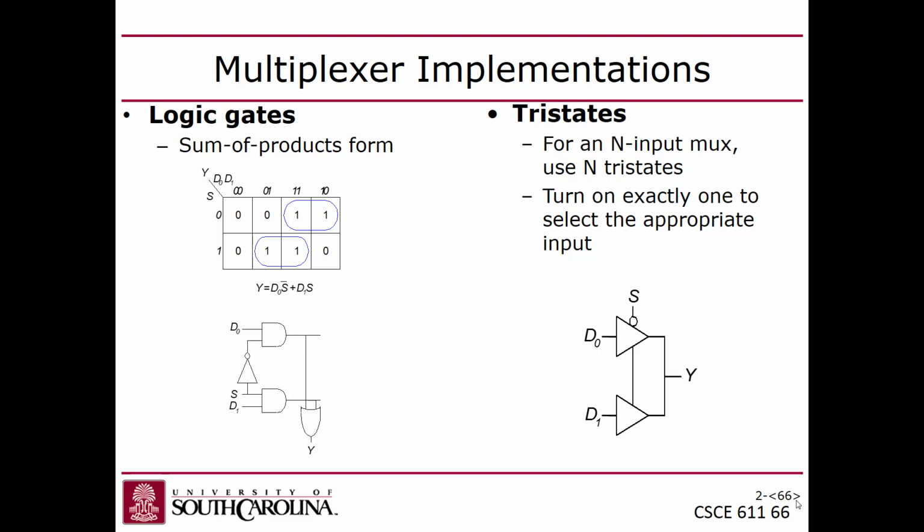Okay. The other way to build a multiplexer is through the tri-state. In this case, you've got two of these tri-states, and you have an input on both. You have D0 and D1 going into the input on two tri-states, and then both tri-states are double driving. Well, it looks like you're double driving the output, but you really aren't, because if you feed the negated form of S into the select of one of the tri-states but not the other, you make them mutually exclusive, right?